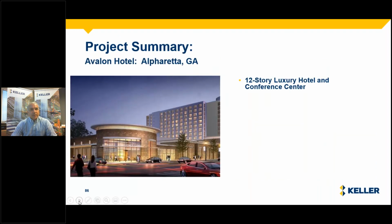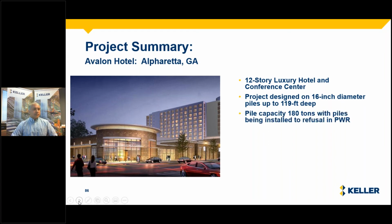We'll jump into a typical project. This is a 12-story luxury hotel in Georgia, United States. The piles were supposed to be 16-inch piles up to about 119 feet deep, that is about 35 meters or so, with 180 tons capacity, with piles installed to refusal in weathered rock. This is like a limestone condition that is in that area.